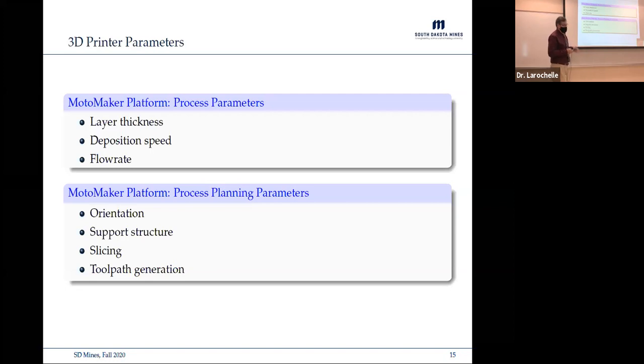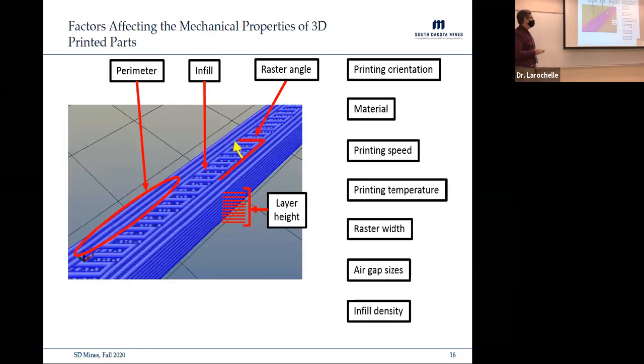Well, when you've got a 3D solid, which direction do you want to slice in? If I'm going to build up a lot of material, which directions do I want to be depositing material with my robot? And then once you've got that figured out, of course I need to plan the tool paths for my robot arm to do what it needs to do to put the printhead in the right place. Well, those are some of the big process and planning parameters that we identified.